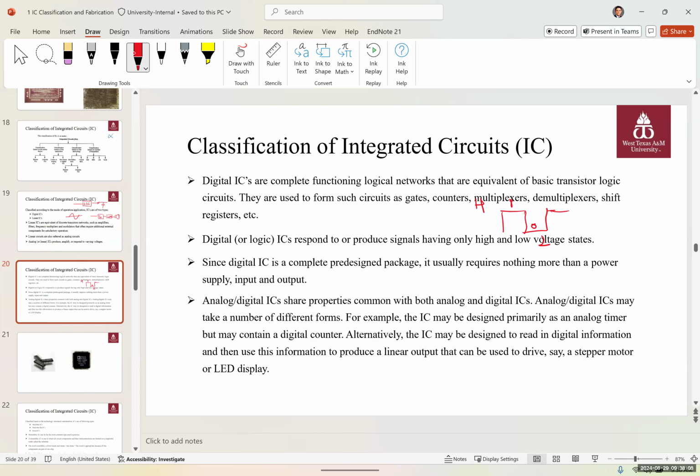These two are examples of digital and analog ICs. You can't determine by the shape if it's analog or digital. You have to look into their data sheet. This particular one, the left one is a digital one, and the right one is an analog. But again, when you look at them, you can't differentiate between analog and digital. They come in different packages, different pin numbers. But we have digital ICs that look like the right one, and analog ones that look like the left one.